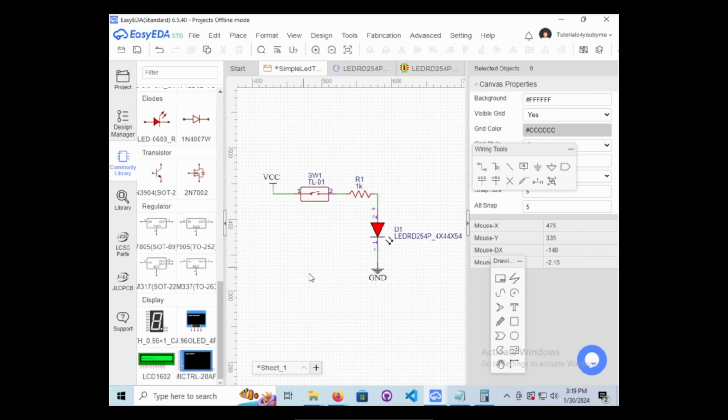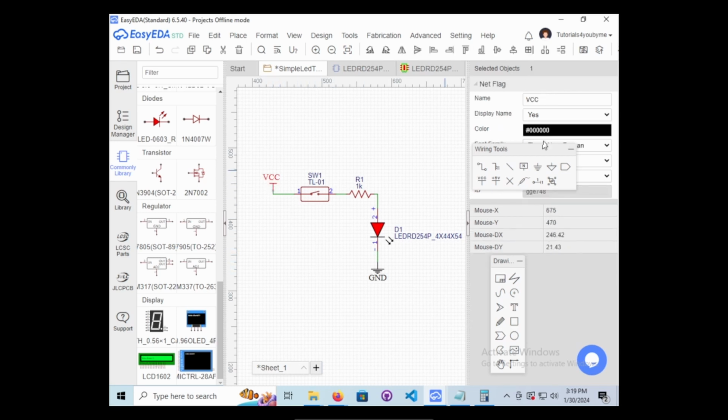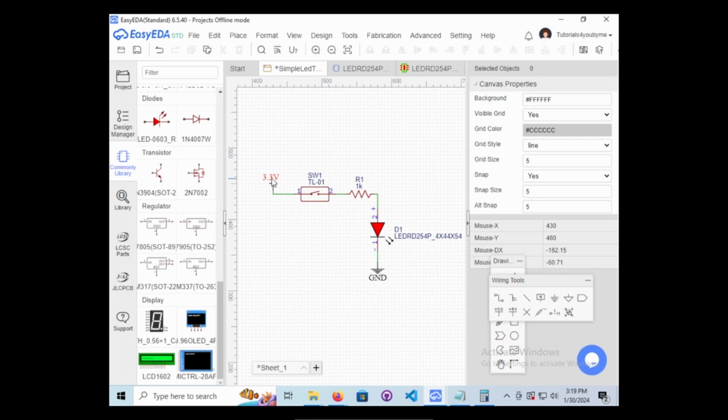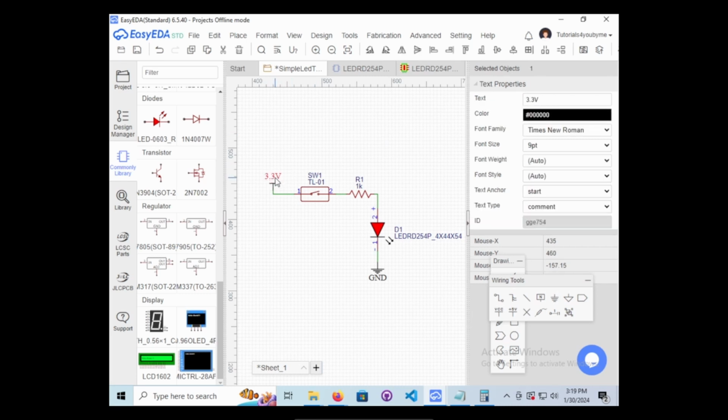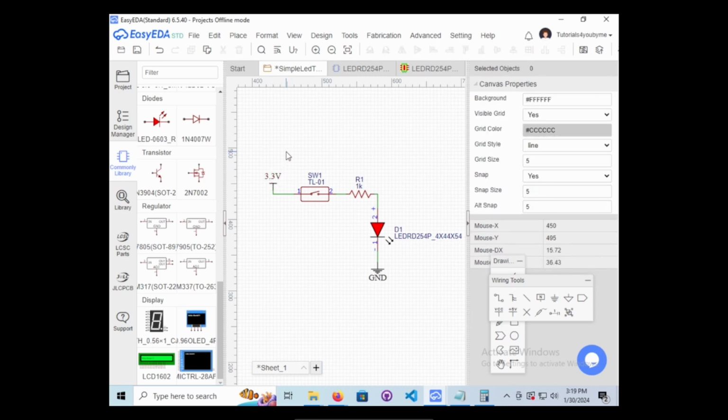So this is your full circuit. VCC. Some people will put a VCC, or they'll say, hey, I'm going to do 3.3 volts, so they'll actually change the name like this. And they usually do this labeling when they're putting tons of different voltages in. Just make it simpler.